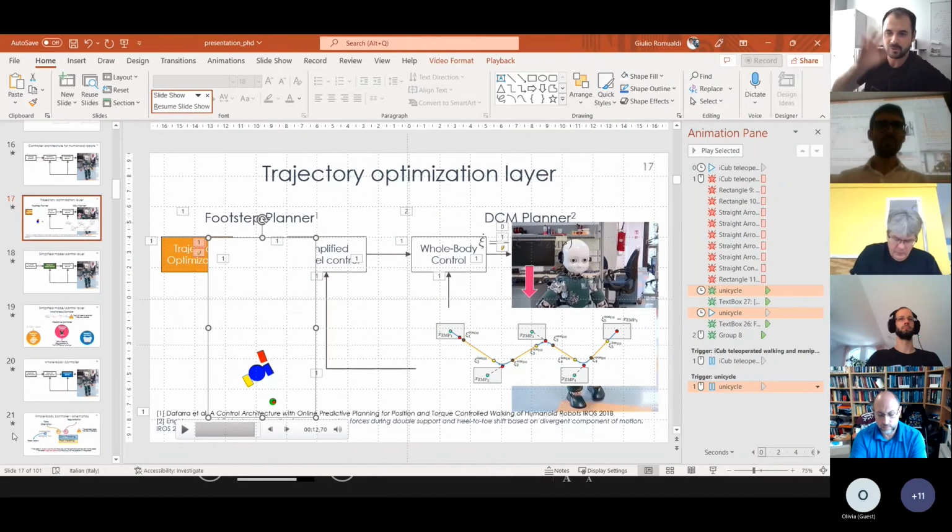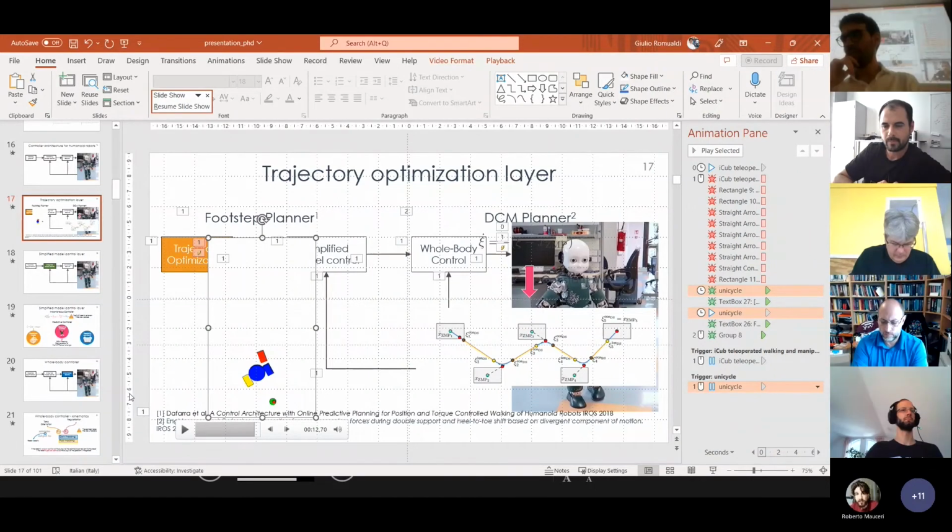I mean, not in simulation, there you have a perfect model, but on the real, actually physical system. Okay, so I didn't present this part in the presentation because it's actually ongoing work and is not completed. We try to identify the contact parameters on a real scenario. So what we try to do is to put the robot on a compliant surface, with one foot on a rigid floor and the other foot on the compliant surface. And there we try to identify the contact parameters.